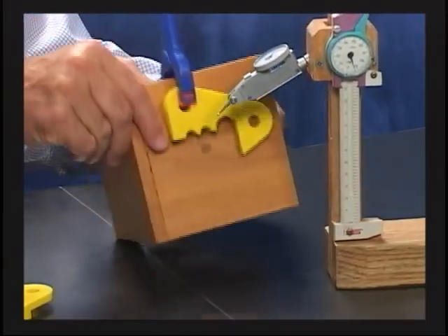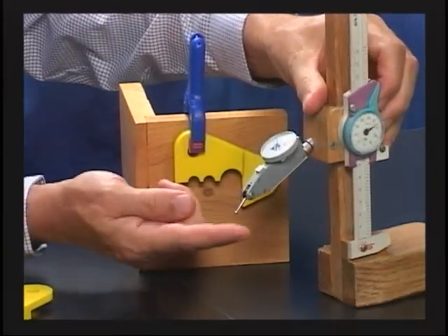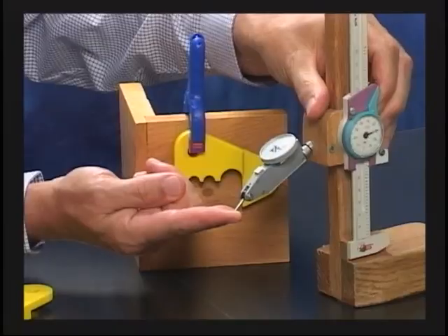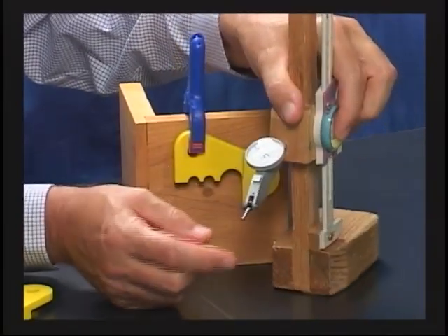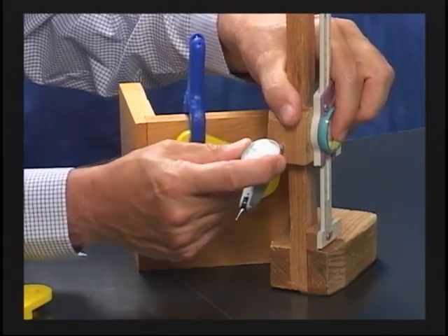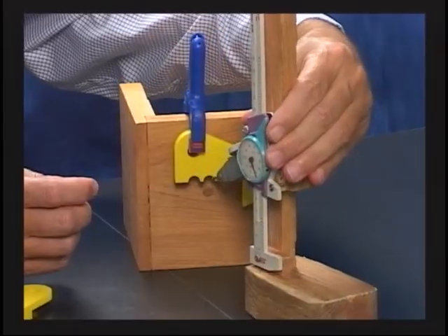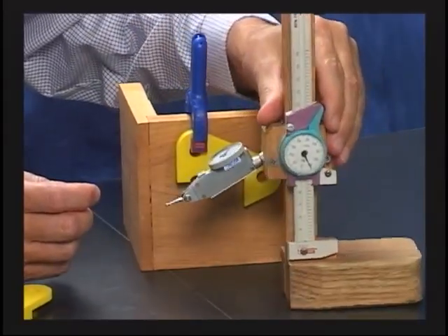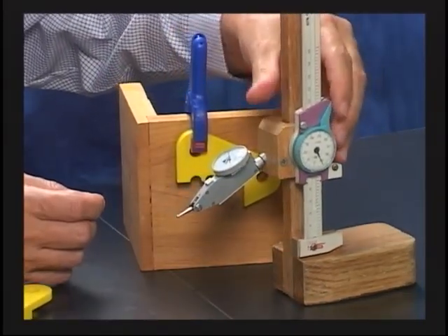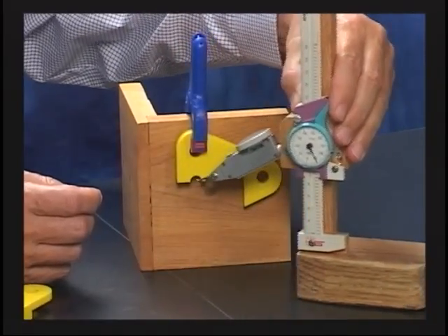And to measure in this direction, remember 90 degrees, I could come in, take my indicator, I have my needle. And this here is a dial test indicator. You notice as I push it down or I push it up, it gives me a reading. I can get where 0 is. I come in, get that bottom surface. And when I read about that bottom surface, what is it? That was the profile. All of those surfaces have to fall within that band of 5. All 3 of them have to fall within.